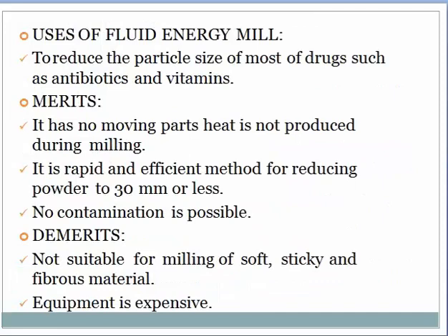Now, use of fluid energy mill. To reduce the particle size of most of the drugs such as antibiotics and vitamins. It has no moving part. Heat is not produced during the milling. It is a rapid and efficient method for reducing powder to 30 micron or less size. No contamination is possible. Its demerits: it is not suitable for milling of soft, sticky, and fibrous material. Equipment is expensive.